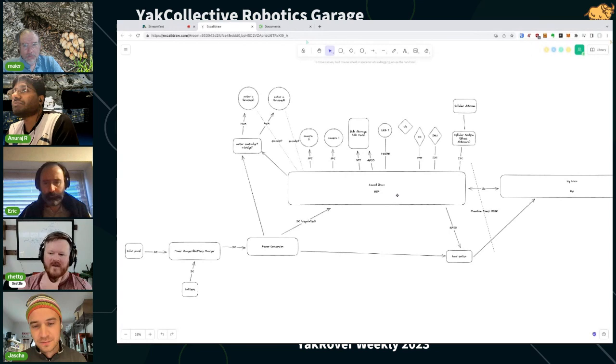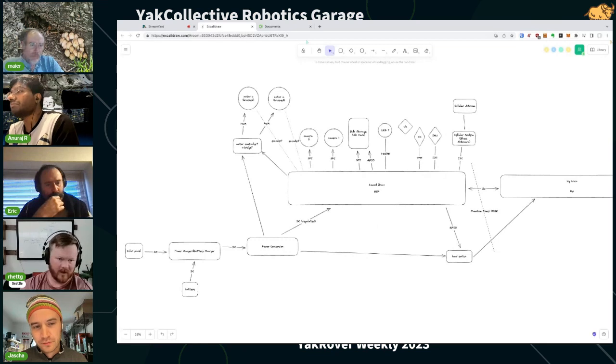Yeah, but the interfaces coming off of that, there aren't that many options, right? It's gonna be an SPI or I2C bus if it's something sophisticated, or it's gonna be a GPIO or PWM type interface, right? And any microcontroller can do that. Of course. That's part of my point, it doesn't particularly matter what micro is used.